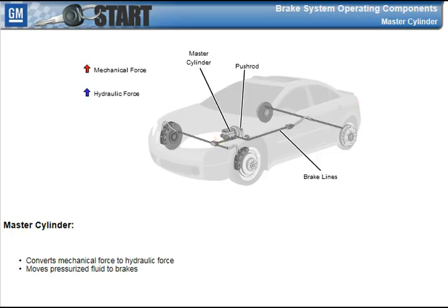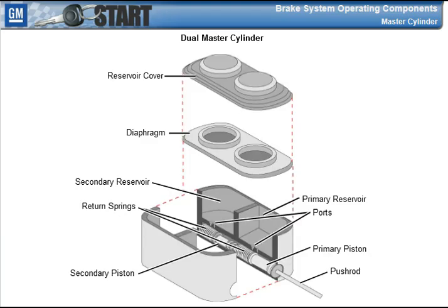The master cylinder is used to convert mechanical force from the brake pedal and booster into hydraulic force, which moves the pressurized fluid through the brake system to the wheels. A dual master cylinder contains primary and secondary reservoirs, a reservoir cover, primary and secondary pistons, return springs, a pushrod, and ports.